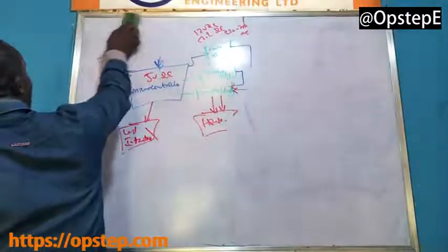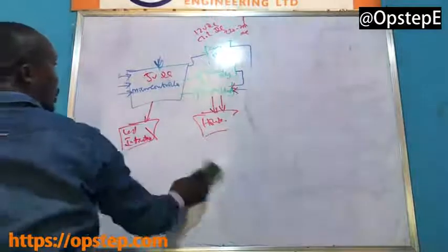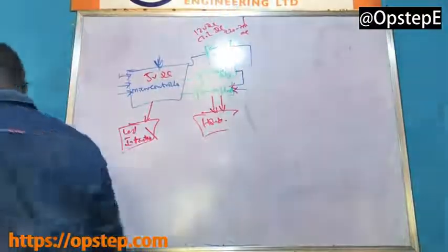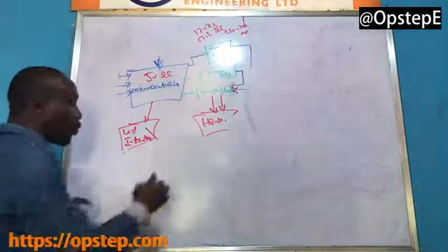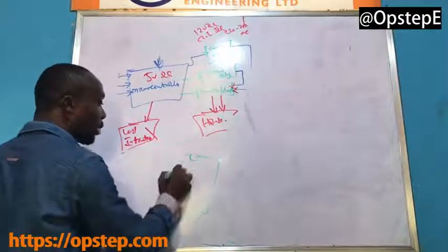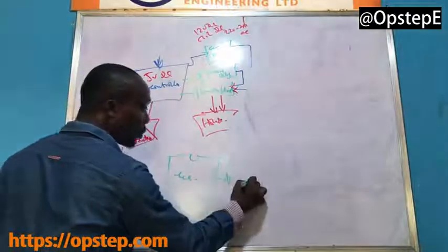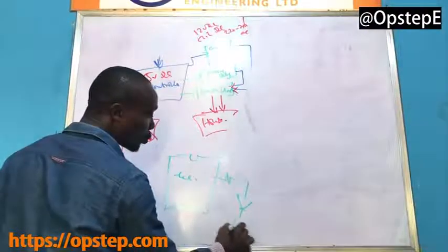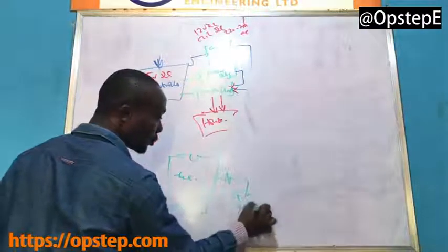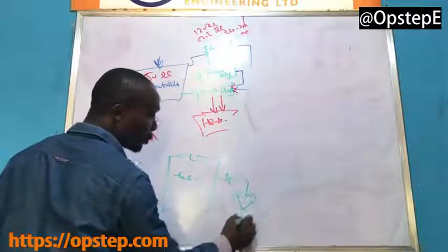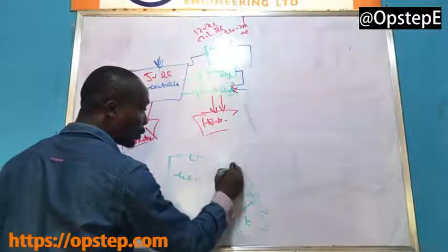So that takes this one out. Now, for the light indicator, how did we get the indicator? From your microcontroller, your MCU, you have a resistor. The resistor then comes into the light emitting diode. Don't forget this is your anode and this is your cathode. This is your 330 ohms.